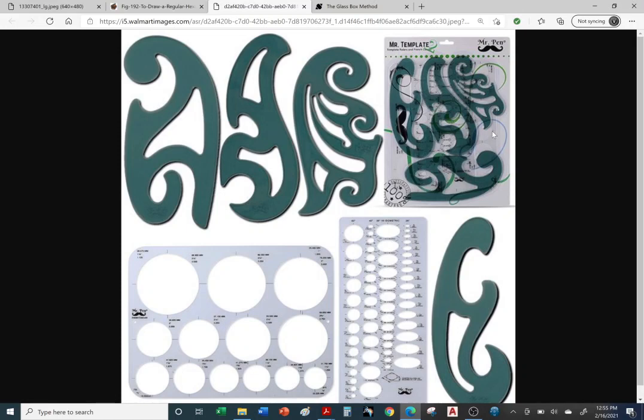Now, one thing I did forget to mention, coming back to these templates. When we were drawing using mechanical pencils or pencils, we would use these templates to draw perfect circles. We also use French curves. In some areas you need to draw some curvature, and you would use part of the French curve to accurately draw your curves and not do it by freehand. We also have templates with ellipses. Why would we use a template with ellipses? Well, this template is specifically made for isometric views. We would use these ellipses to draw our holes.